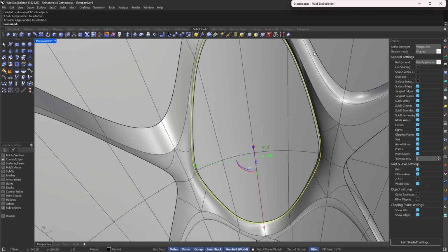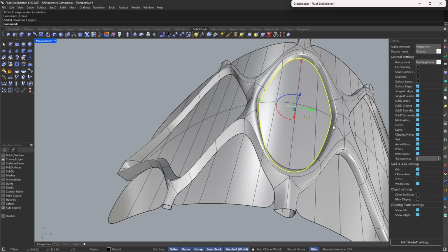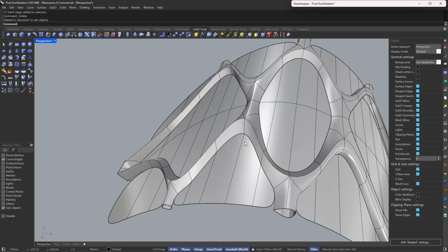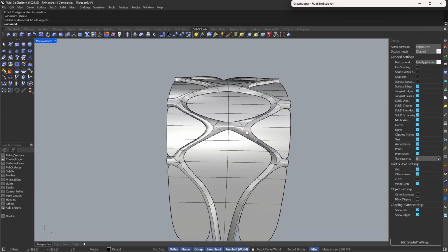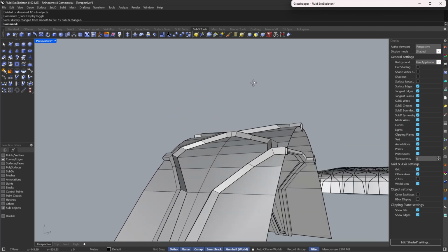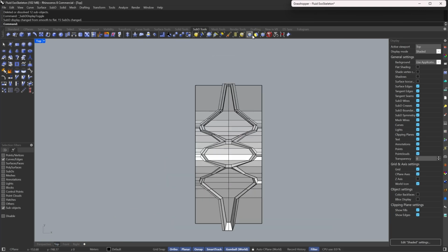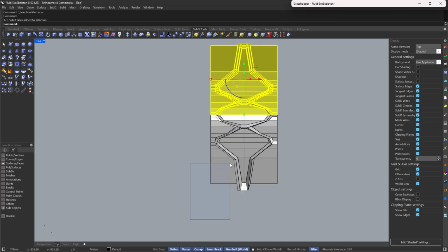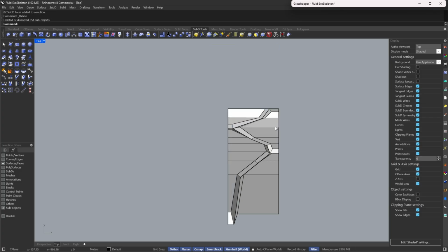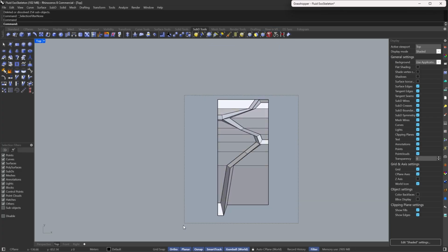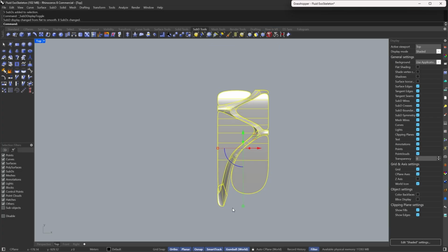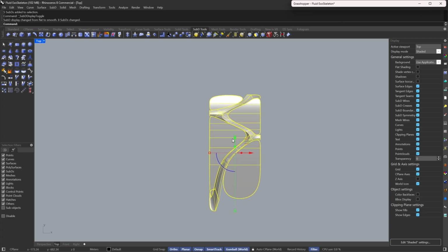I'm going to eliminate this, crease this in the middle, and eliminate this. Right now I think I have my quarter ready. I don't need anything else for the quarter, so I'm going to delete all of these other faces. I don't want them, and also in here I don't want this. I'm only interested in this quarter, and this quarter is going to work with me for everything.